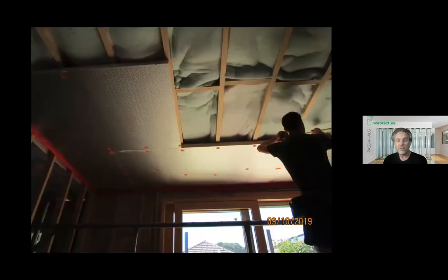Then we've got a shot. We've jumped forward a bit in time, but this is how the ceiling was put together. So the roof is insulated. You can see the polyester batts up in the roof there, and then these are sheets of PIR, which is a rigid insulation board. It's got a foil face on it. And I think I didn't put the photo in, but all of the joints of that get taped. And that's how we create airtightness on the ceiling in this particular building.